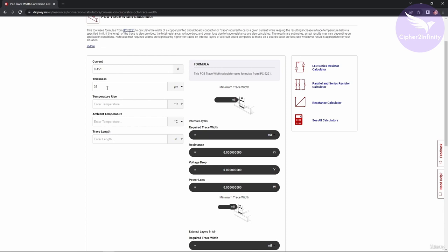Most of the manufacturers which manufacture the PCB, on their website you will find this particular value as a default value for the thickness of copper which will be there on the dielectric. So that's why I am entering this value, and this value is also called finished copper thickness. So we are going to use a PCB on top of which the thickness of copper is going to be 35 micron. And we need to include the same value here, which is what will be the thickness of copper on the PCB. So we have entered that value, 35 micrometer.